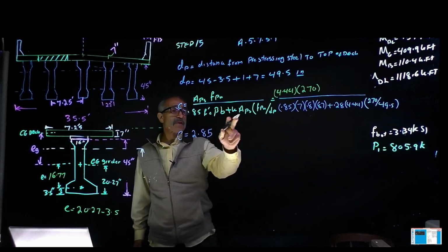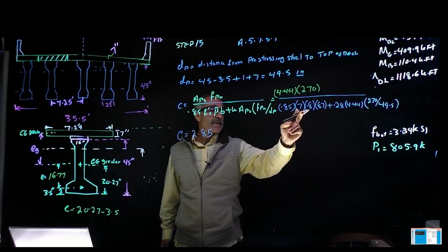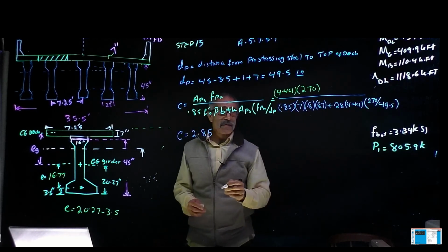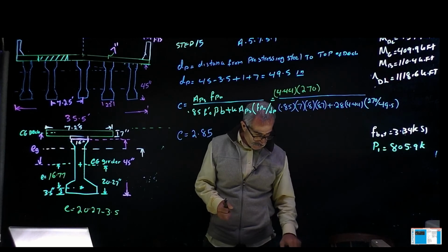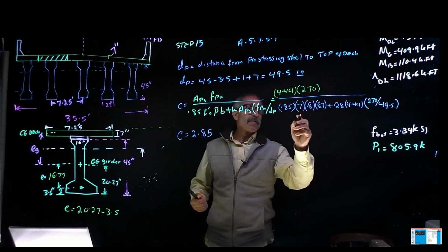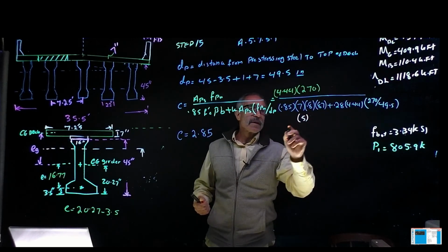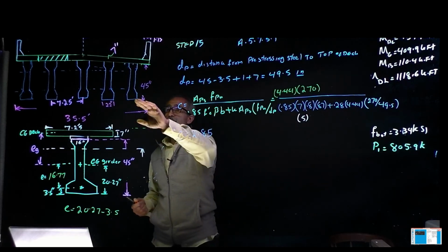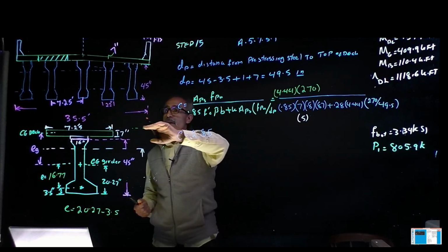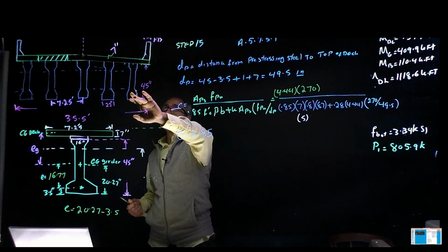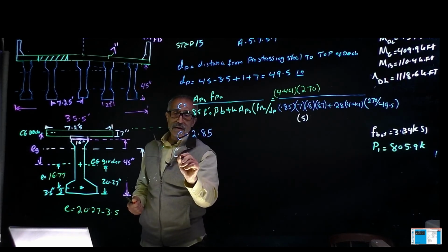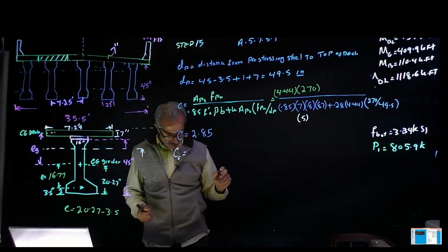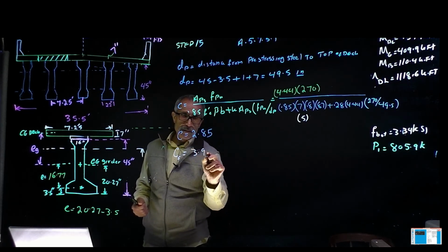And if we use 5 in here instead of f'c, if we use 5 right here, because at the beginning we used 5 for both of them, then halfway through we knew that it's not going to make it, so we changed it to 7. If I use 5, that's going to come out basically 3.96 inches.